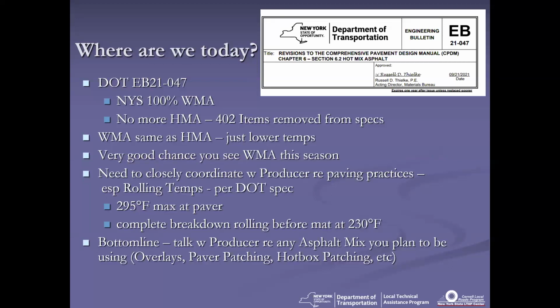DOT does not use hot mix anymore. We've removed that item from our specs. We are exclusively a warm mix state. You get the same benefits or more, just at lower temperatures. The key you want to remember when you're working with warm mix is 295 max at the paver, and you've got to complete your breakdown rolling before 230. You've got to talk to your producer before you put any mix down, because you need to know whether you're using warm mix or hot mix, and especially what your applications are going to be.